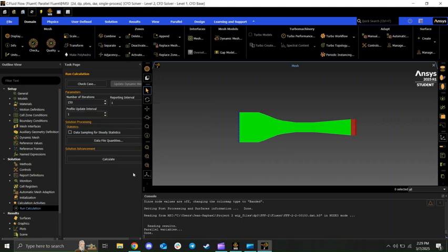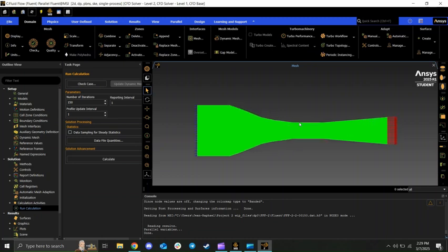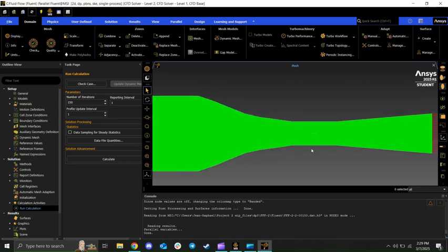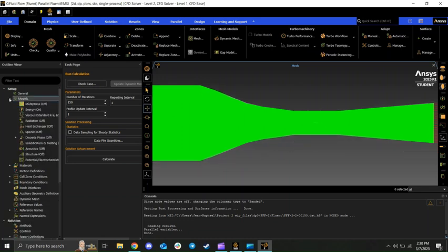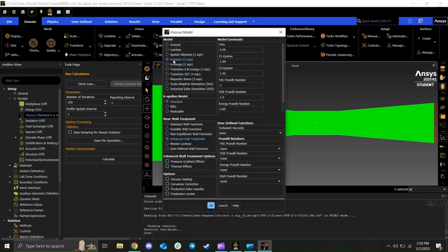Excellent. Okay, so then here's our mesh for the wind tunnel. Inverted zooming in controls. As you can see, there is the blockage. So then what we would do, setting up, making sure our models are all working, our energy is set to on. So right click, there you go. We know we're in viscous. Make sure that, like the previous lab, it is set to k-epsilon that we are measuring. Standard enhanced wall treatment for better measuring of values. Just click OK.